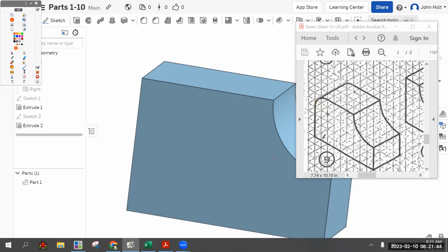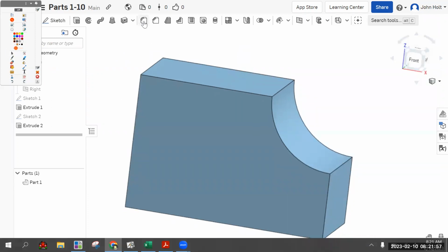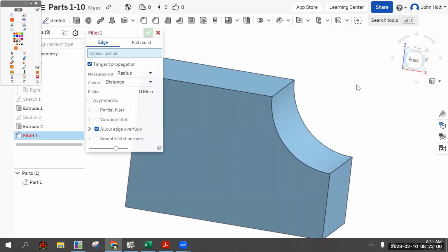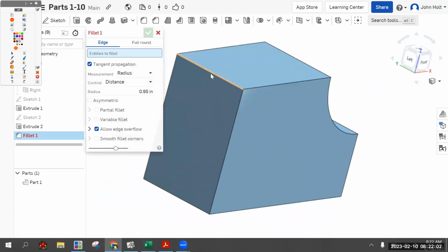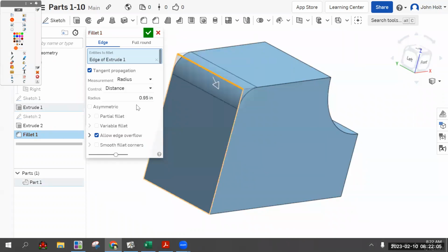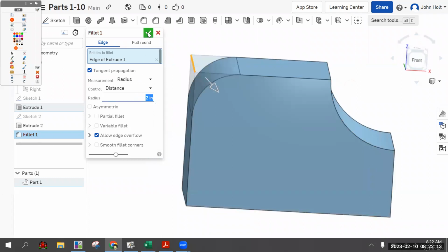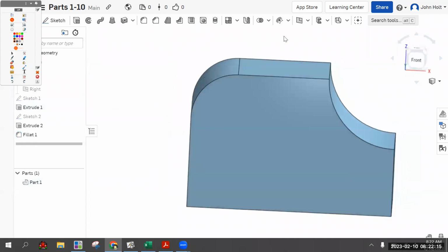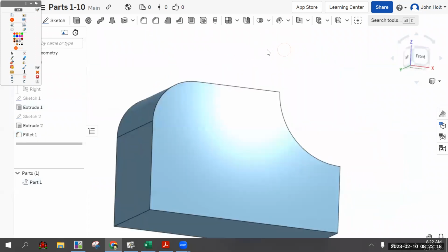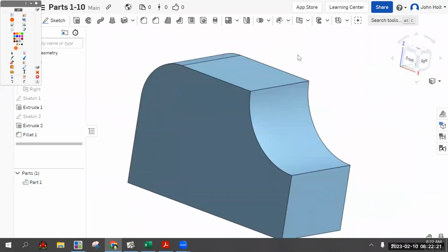And we could do a circle and try to get it to line up exactly, dimension the center point and cut extrude everything else. Or we could just use the fillet tool, which is this tool right here, and fillet this top corner here, or this top edge. And the dimension we want is that radius of 2. And hit OK. And there you go. So that's part 9, all done.